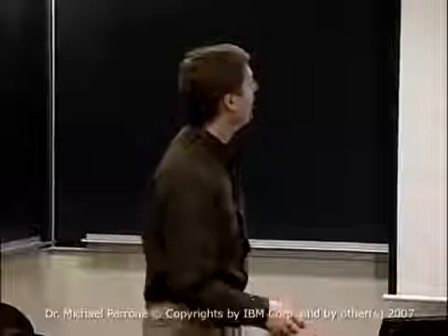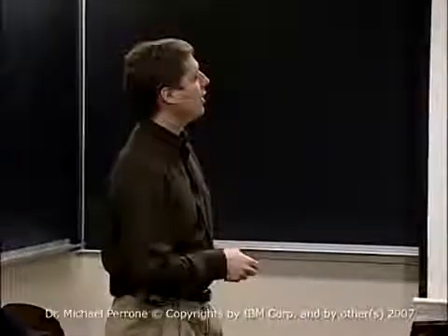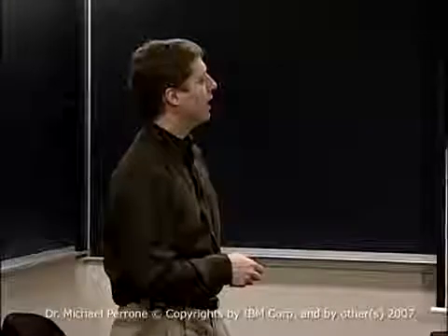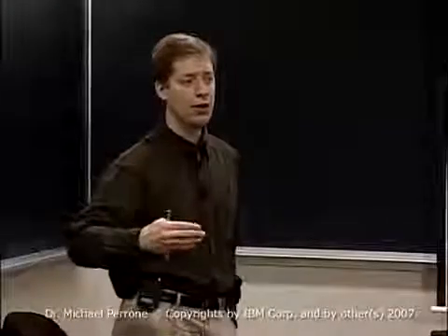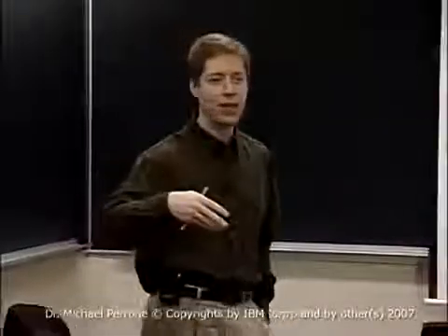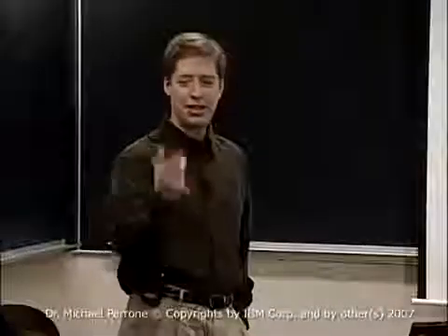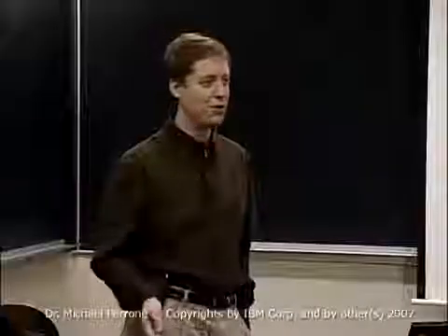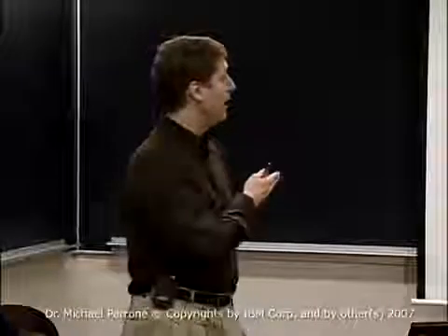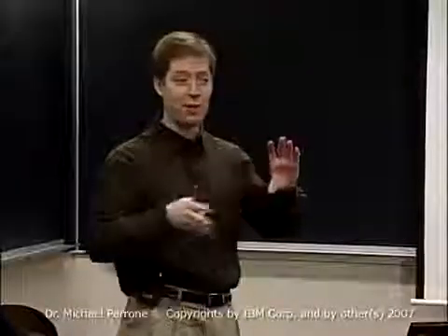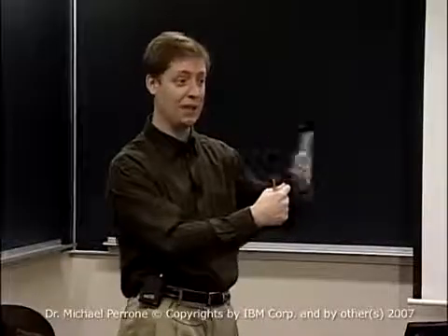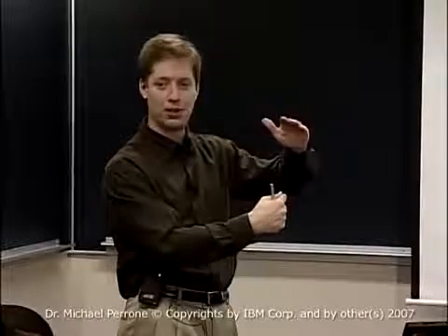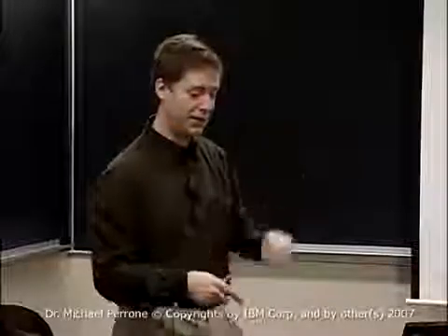And oh yeah, the DMA engines here. Each DMA engine can have up to 16 outstanding requests in its queue before it stalls. So you can imagine you're writing some code, and you're sending things out to the DMA, and then all of a sudden you see really bad performance. It could be that your DMA engine has stalled the entire processor. If you try to write to that thing and the queue is full, it just waits until the next open slot's available. So those are kind of considerations.